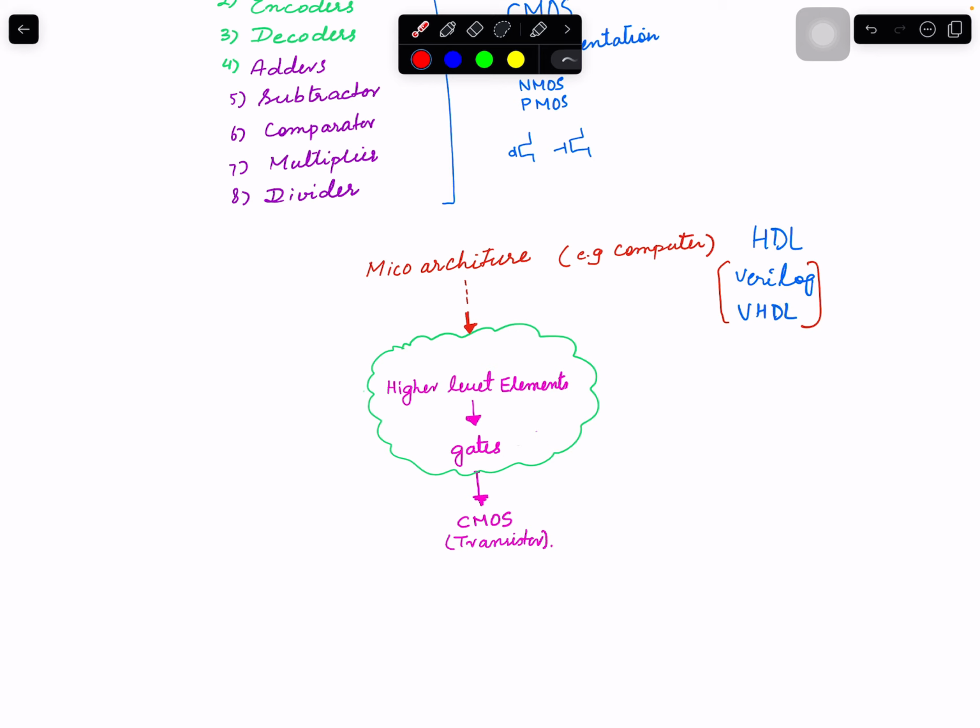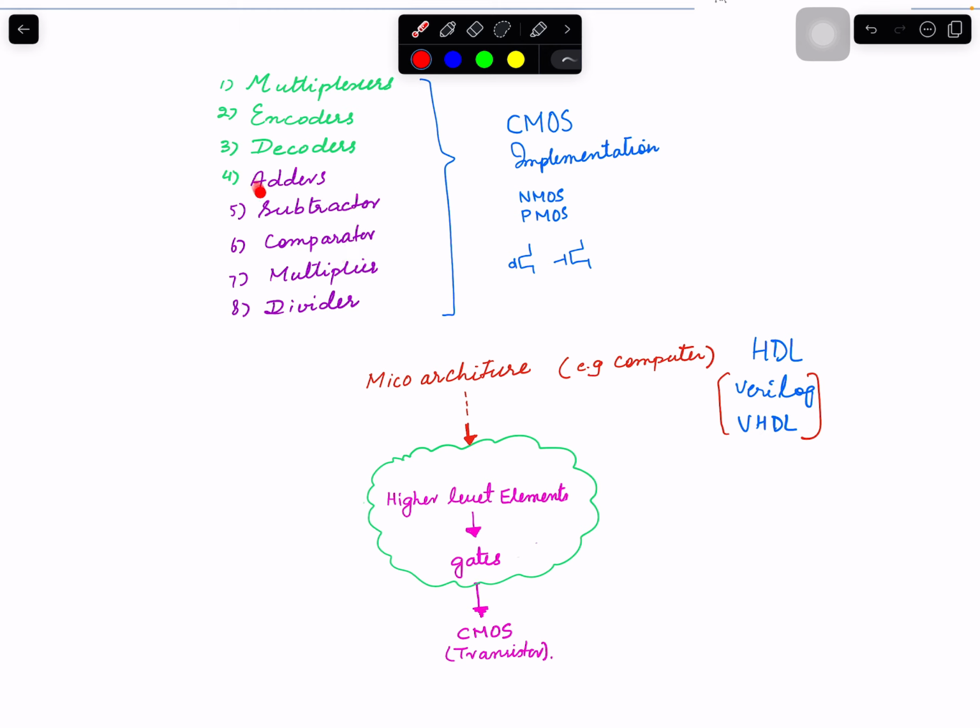You simulate that design using simulators to verify that it's really doing the functionality that you designed it for. But once you have defined it in HDL and you want to convert that into transistors, you can convert it into an intermediate format. So the basic building blocks, some of them can even be logical gates like AND or exclusive-OR. Those types of functionality can be described with different logic gates. So arithmetic and logical gates are used under the hood.